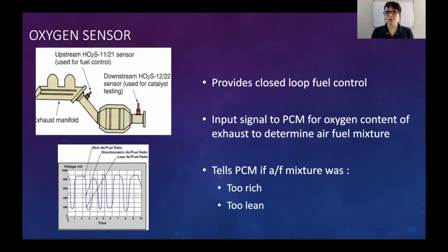Oxygen sensors are super duper important for what we call closed loop operation. If your engine doesn't have the information from the O2 sensor, your AFR or air fuel ratio sensor would also fall into this category, it is going to have a hard time knowing if the decisions it's making are good, and so they tend to go into a default mode or an open loop mode.